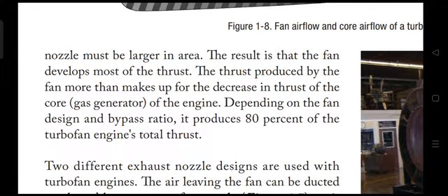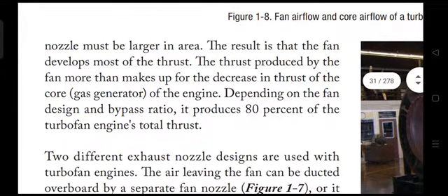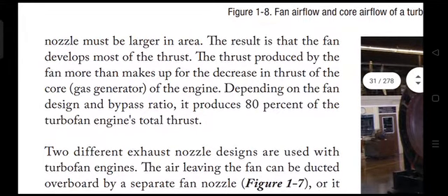Gas generator means something that is producing the gas. Gas is what? It is the burnt air only, air burnt with fuel. So who is producing the gas? The compressor is compressing it, the diffuser is diffusing it, the combustion chamber is burning it, and through the turbine it is going out, expanding, and then finally going out. So the entire process, from compressing till exhaust, is basically the portion where the gas is produced. All these processes are gone through and the gas is produced. So that is called the gas generator.